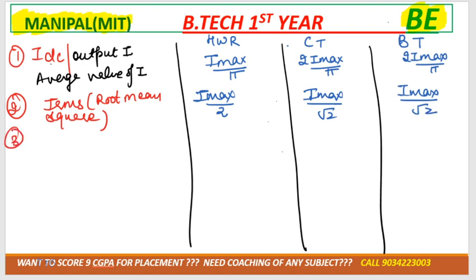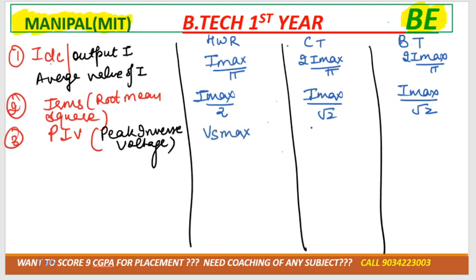Next they can ask you the peak inverse voltage. Peak inverse voltage is also denoted by PIV. So for this particular case, PIV is Vs maximum for half wave, that would be 2 Vs maximum for center tap, and in this case Vs maximum. Mostly you can see that center tap and bridge type are the same, but here keep this in mind.